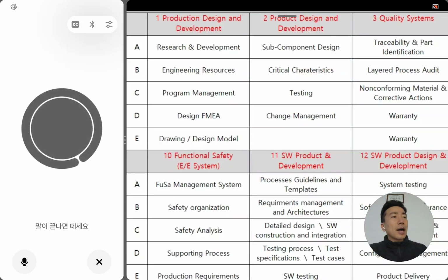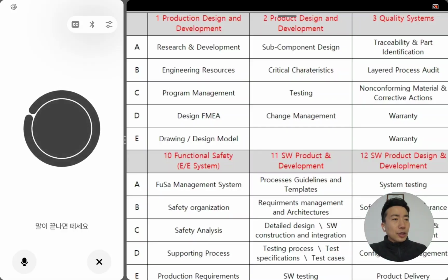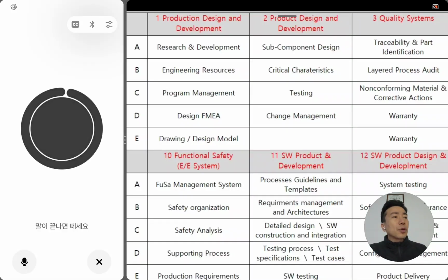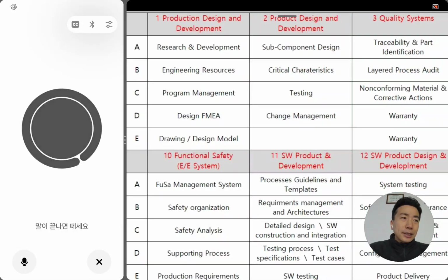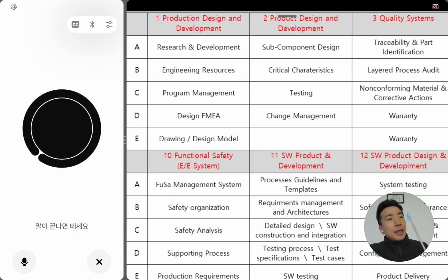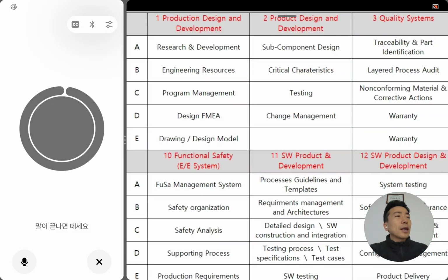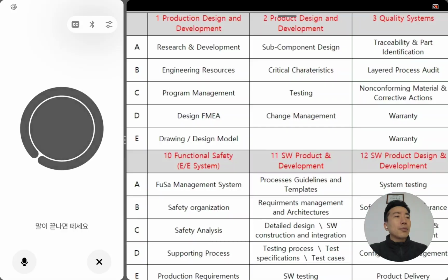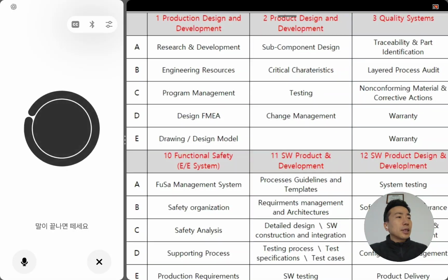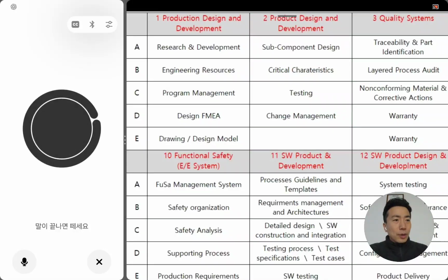Potential failure modes are identified and evaluated based on the severity, occurrence, and detection. And appropriate mitigation actions are defined for high-risk items. DFMEA results are documented and managed in our PLM system, so they are fully traceable and accessible to all relevant team members. These DFMEA outputs are also used as key inputs for PFMEA during process development.